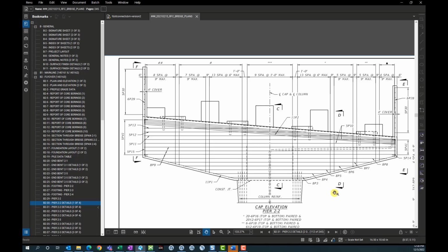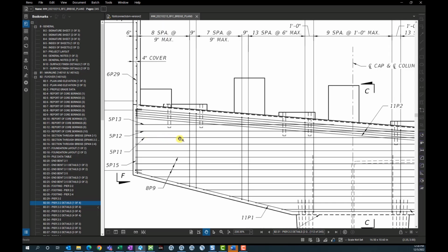And there are some pretty big benefits to doing that because ProConcrete automates a lot of things. It actually automates the labeling of all this stuff. So if you cut a section through this pier cap or in front and then point towards the pier cap, it'll automatically re-symbolize all the 3D bars into these center line of bars here.